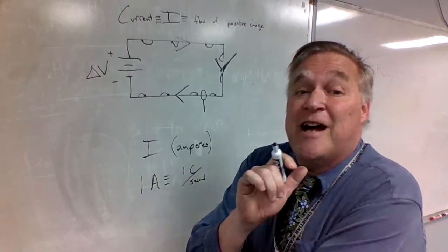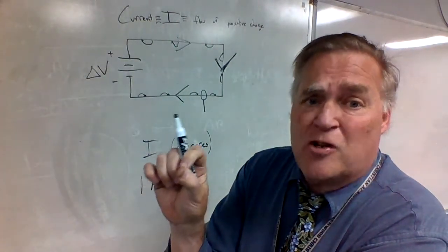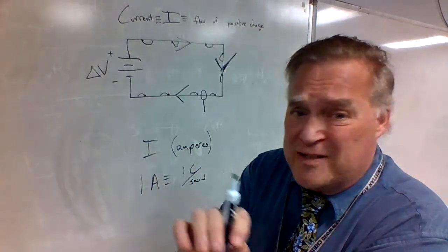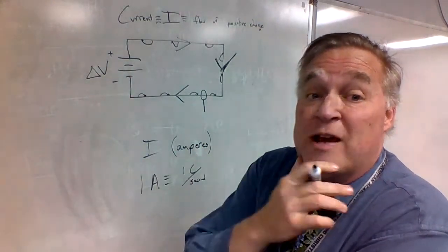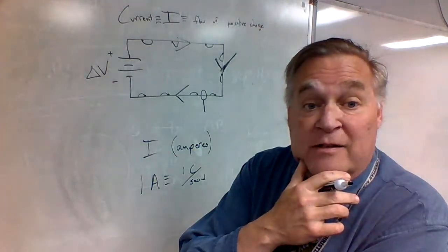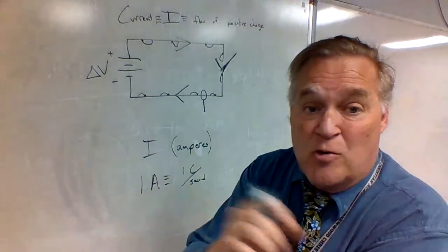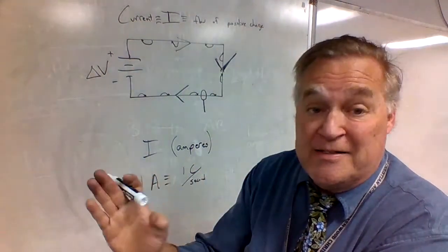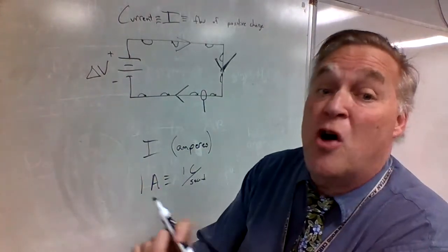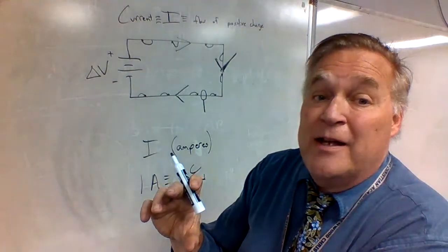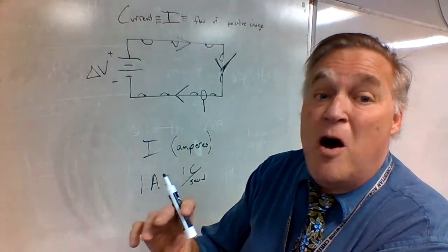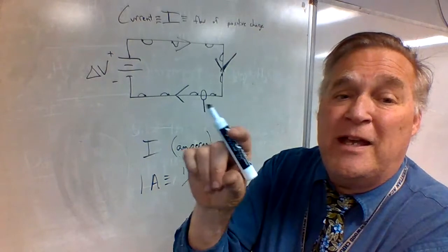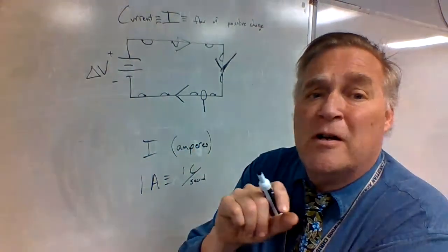It's always on the surface of the conductor. And that's why the cross-section of a conductor is often a circle, not only because it's easy to machine that way, because it draws through a die and you can change it to whatever gauge you would like. Different diameters correspond to gauges, and a gauge corresponds to how many dies you pulled it through. Because you can pull too hard on copper. You can try to take a copper rod down to a place that's too small in one step, and the copper will break. So gauge corresponds to how many times you drew that copper through a die.